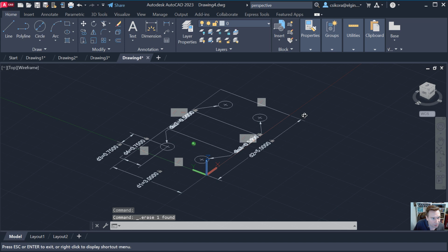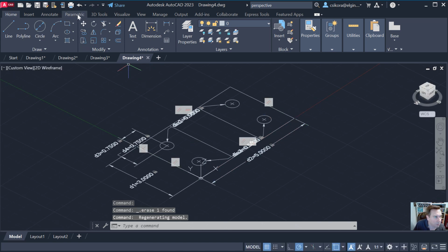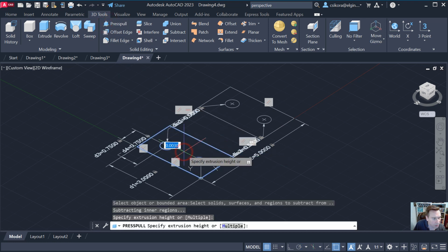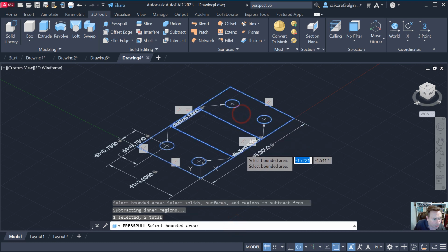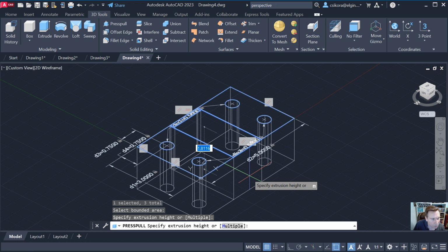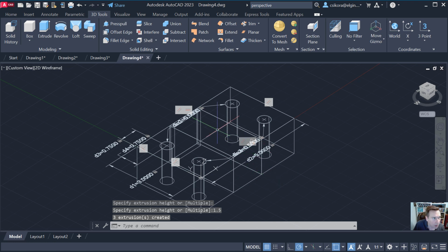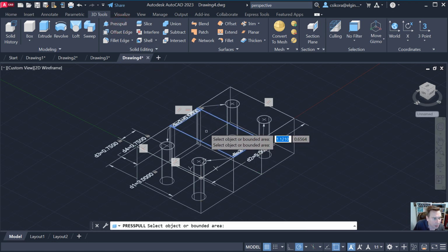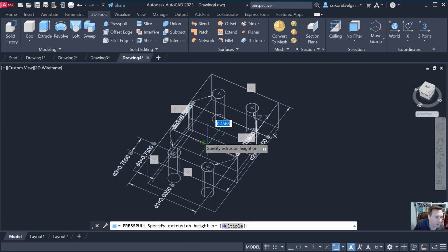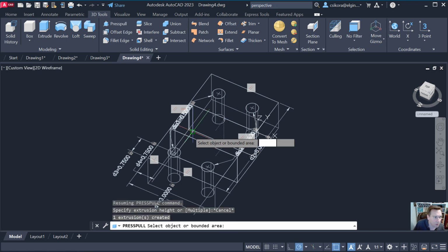And now we could rotate this, and let's do the press pull. So we could select this. Now if there's multiple, select multiple right down here, and select this, and that. Now hit enter, and drag it all down. And we want this to go a depth of 1.5. And now let's go to press pull again and just capture that center. And isn't that interesting? Because of the dimensions, it's interfering. Let's hit escape there.